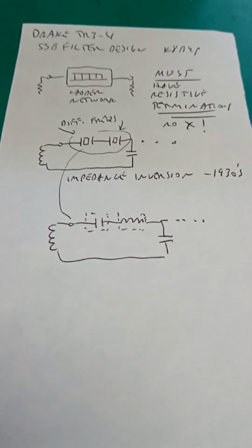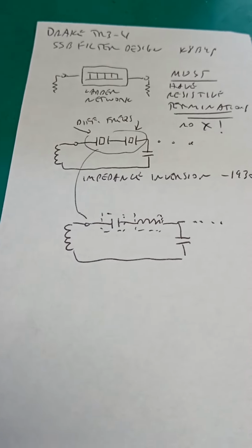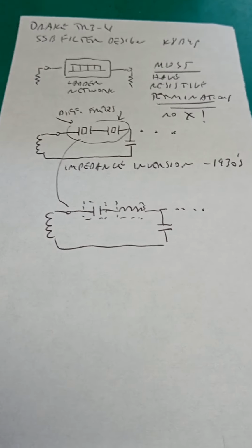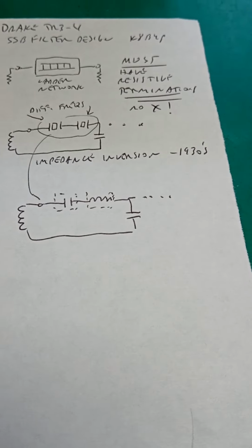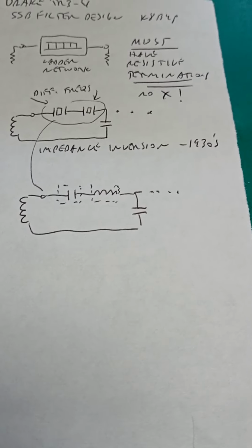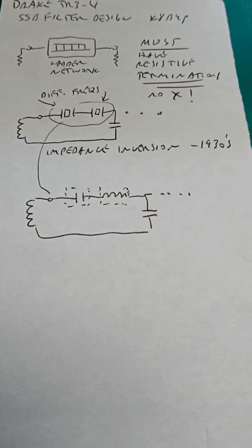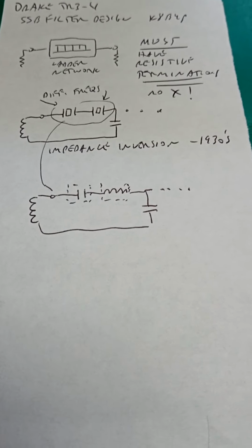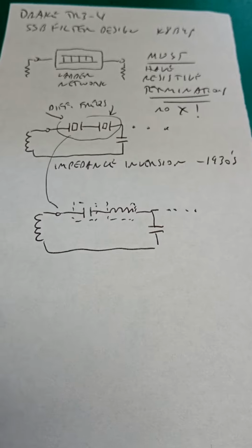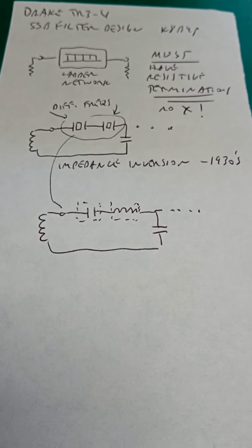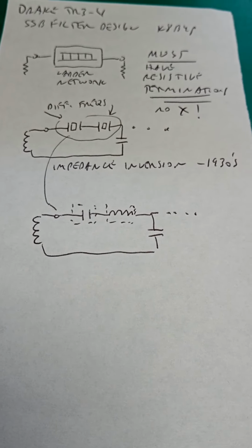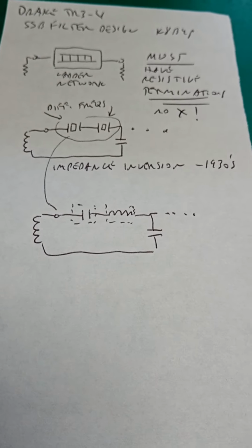But as far as I know, and I spent years looking, nobody has filter crystals for these radios because they're at 9 megahertz. And there's essentially nothing made at 9 megahertz these days. You can buy oscillator crystals at 9 megahertz, but don't try to build a filter with them because they're too lossy. I had to order very special crystals from an original manufacturer that had a few that I tested had between 6 and 9 ohms resistance, which is extremely low.